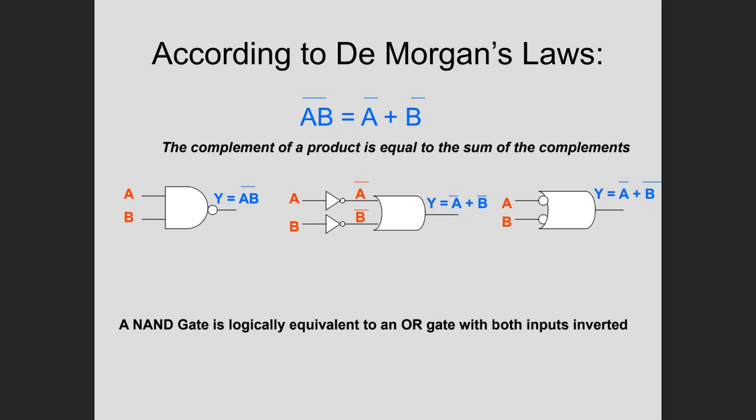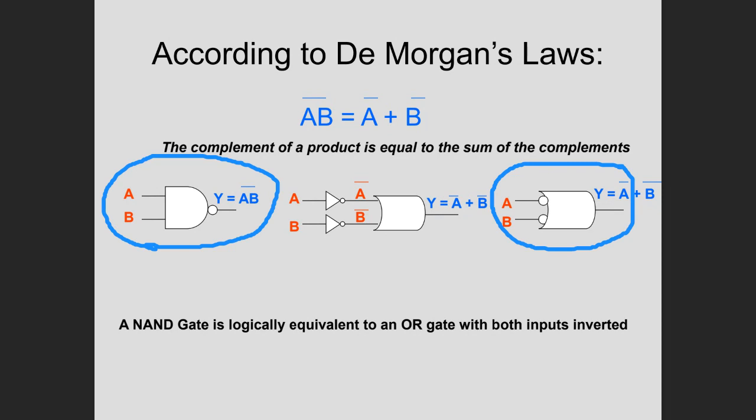But basically, what this does is it takes a gate. Now this is our NAND gate. It takes our NAND gate and it changes it to one of our OR gate. Now this OR gate is interesting because if you think about it, when I showed you the OR, it looked like that, right? And then if you put a bubble on it, then it changed it to a NOR. So that would be like taking A and another variable B, and you will OR those together. That ORs them together. But then when you add that bubble to it, you're NOTting this. Whereas what I have right here is that's not that.